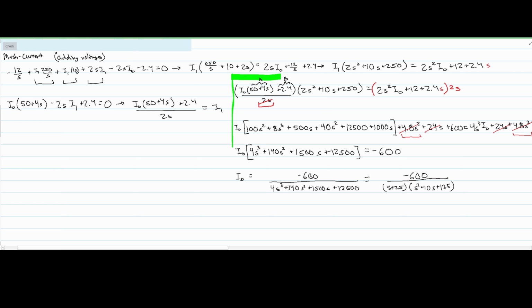So now dealing with complex numbers, this is going to give us this. We'll have a negative 600, and then if we use the Symbolab calculator, we are going to get two possible values. We are going to get first that, and I'll write this over here, s is equal to a negative 5 minus 10j. And so that is the first if we have a negative. And now if we switch our quadratic to be the positive part, we're going to have that s is equal to a negative 5 plus 10j.